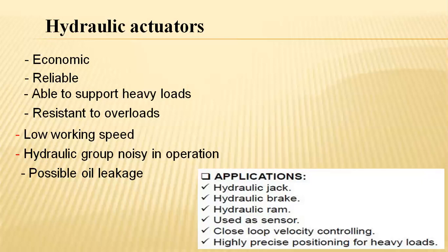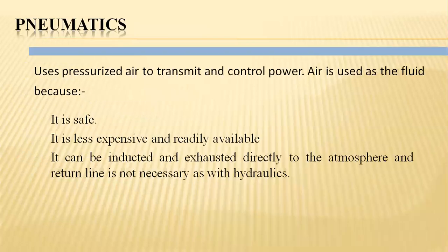But the limitations here are a low working speed that maintains only slow actions, and the entire hydraulic group makes them noisy in operation. And if there are any deflections at the connections, the oil leakages will take place here.